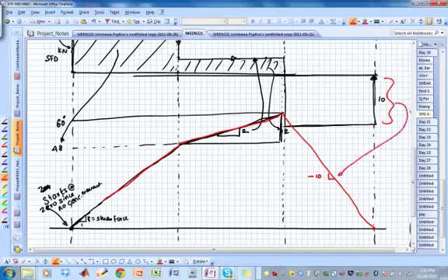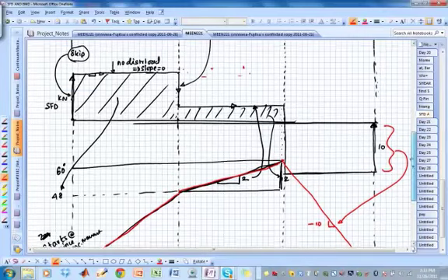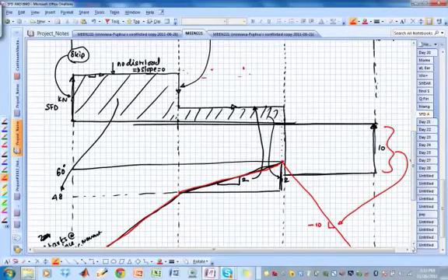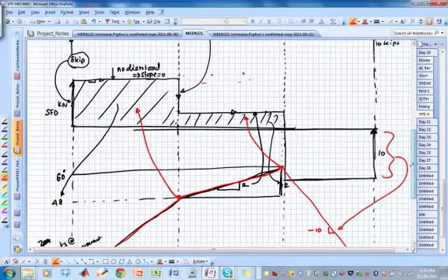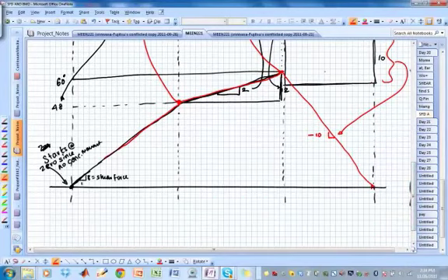So did you see how I got the bending moment diagram? So I use the slope to draw the line. I use the area to find this point. So this point is given by this area. This point is given by the sum of these two. And this point is given by the sum of this and this and this. You will see that the area here will be exactly equal to the areas there. So I'll get 0. Okay. So that's how you draw the bending moment diagram. I hope you got this idea.